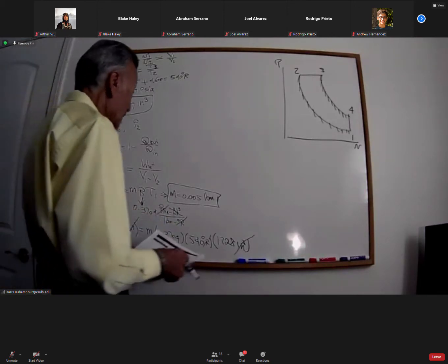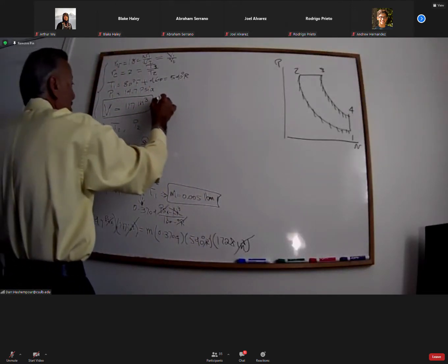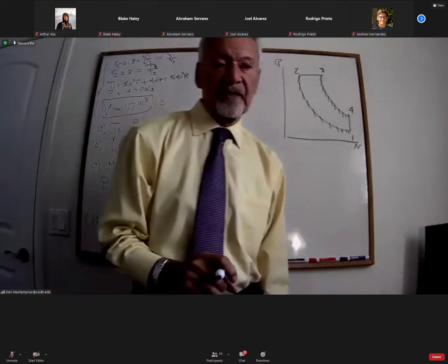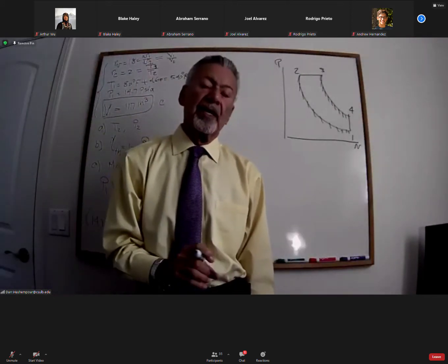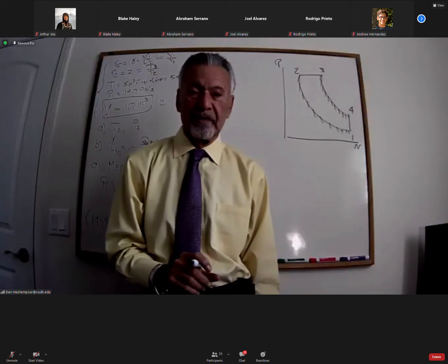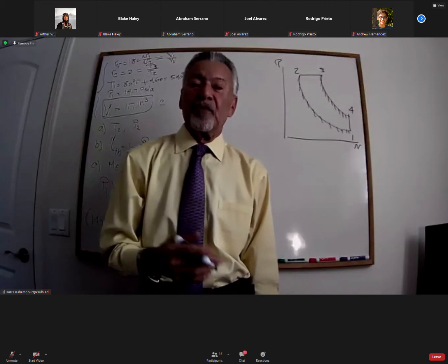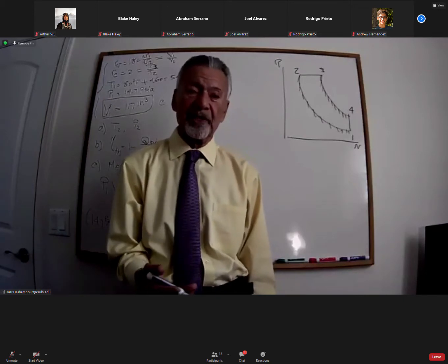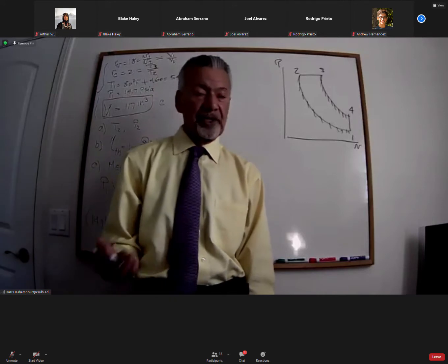One thing on the given part that I missed, which is very important for reading the problem carefully: in this problem, they say assume cold air standard. What does it mean? We know that Cp and Cv are a function of the temperature. As the temperature goes up or down, they change.